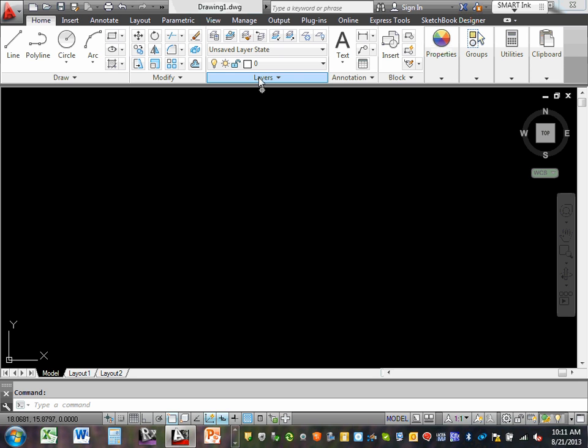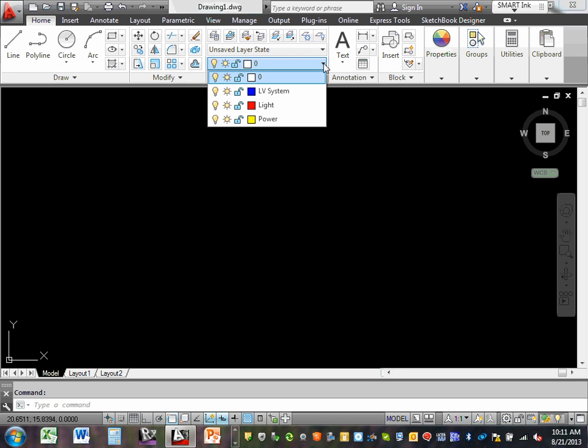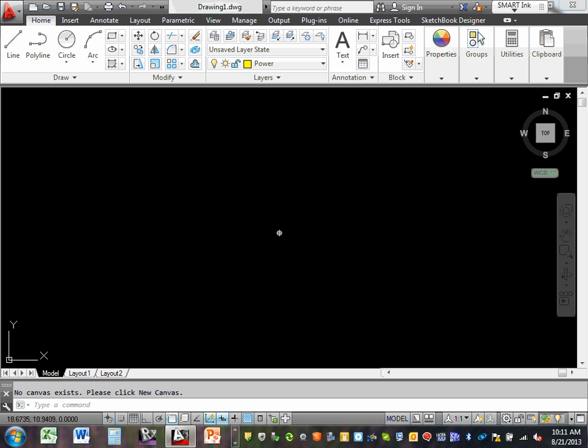Now do me a favor. We're going to go draw a couple of things. Before we start, when you guys start placing your receptacle or your power, before you even do anything, you're going to go right here, set yourself on the right layer. Look, can you guys see the layers that we just created? Everybody can see them? Okay, I'm going to do a receptacle or something power. So go set yourself on power. Can you guys see that? So now I'm setting for power.